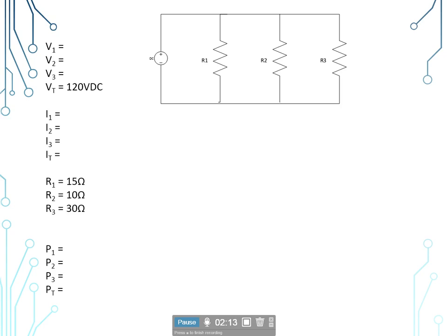But if we used it, we'd have to do R sub 1 times R sub 2 divided by, open your parenthesis, R sub 1 plus R sub 2, and then that answer would become R sub 1 slash 2, and we'd have to do another product over sum, R sub 1 slash 2 times R sub 3 divided by, open your parenthesis, R sub 1 slash 2 plus R sub 3, to get our total resistance.